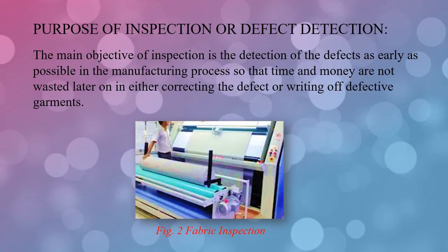Purpose of fabric inspection or defect detection. Fabric inspection is an important aspect followed prior to garment manufacturing to avoid rejects due to the fabric quality and facing unexpected loss in the manufacturing. Fabric inspection is done for fault defect detection, or for color, hand or feel, to check out the length or edge shading, and many more. So fabric inspection ensures to minimize the rejection of cut panels or rejected garments due to the fabric faults. Although the purpose of fabric inspection is to determine the quality and acceptability of garments, as fabric is received, it should be inspected to determine acceptability from a quality viewpoint.